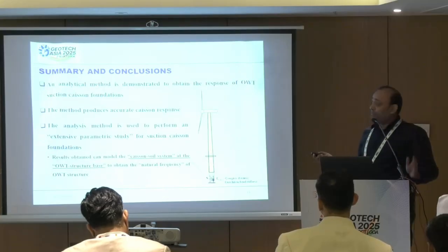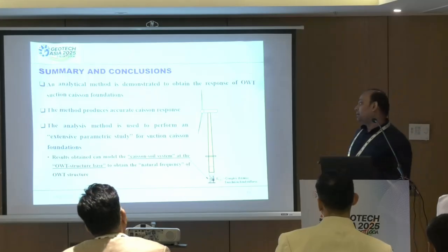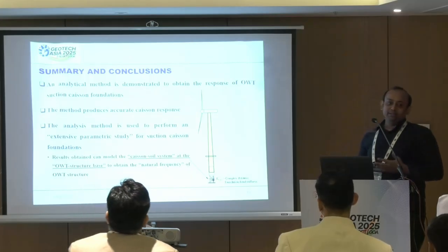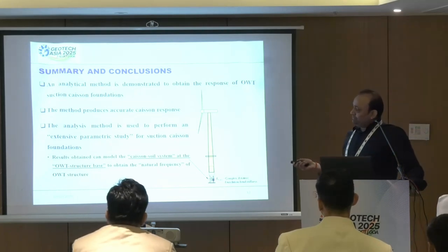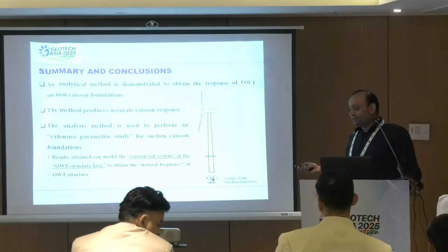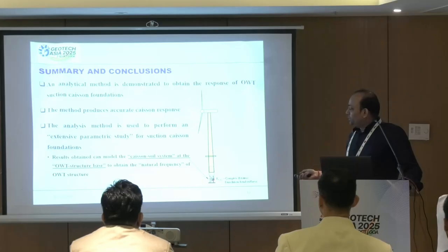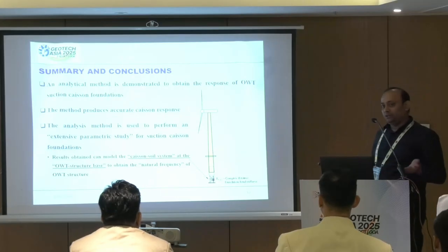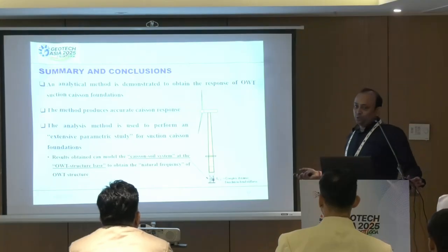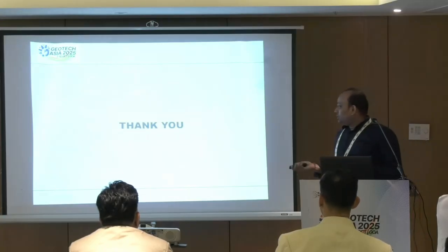So this was all on the paper. So, summary and conclusions from the paper: an analytical method is developed, and we found that the analytical method is accurate. The analysis method is used to perform an extensive parametric study for suction caisson foundations. Results obtained can model the caisson soil system at this particular point, and then as geotechnical engineers or structural engineers, you can use this input from geotechnical engineers to calculate the natural frequency of this offshore wind turbine structure. So this was all from the presentation.